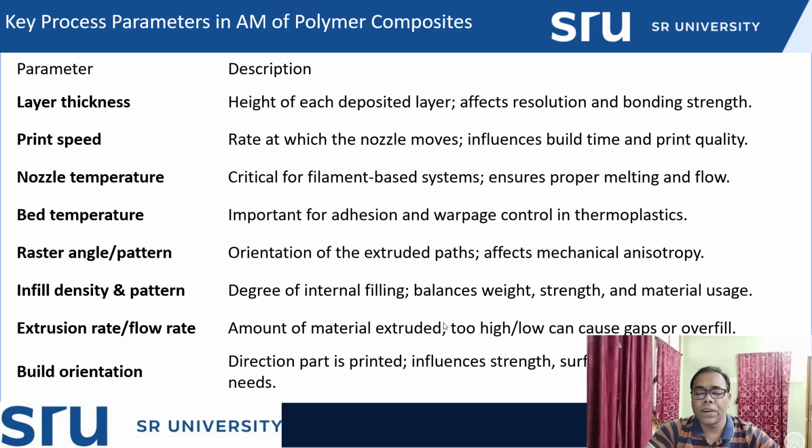Similarly, infill density and infill pattern. In case of the infill pattern and infill density, first one should understand the meaning of infill density. Infill density is nothing but how much of the inside is filled with material when it is printed. Suppose you are taking 100% infill density, then complete printing of the inside takes place, so it will be completely solid material.